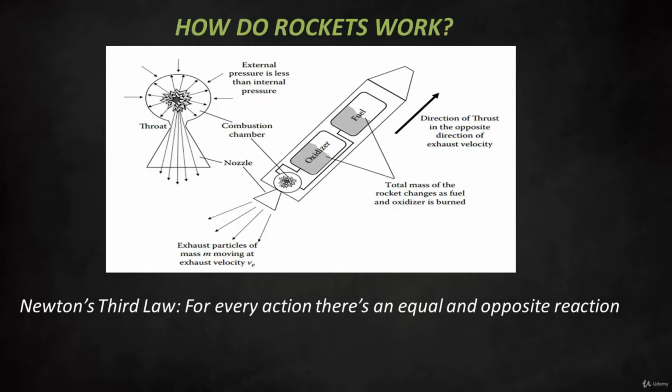After heating them up, they will vaporize and we've got hot gases inside that combustion chamber. Due to the great amount of heat that was transferred and the really high temperature there, we've got a high pressure. Those hot gases inside the combustion chamber will try to get out through that nozzle, because the ambient, atmospheric pressure surrounding the rocket is less than the pressure inside that combustion chamber. So the gases will try to get out.